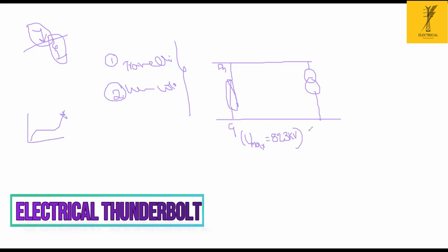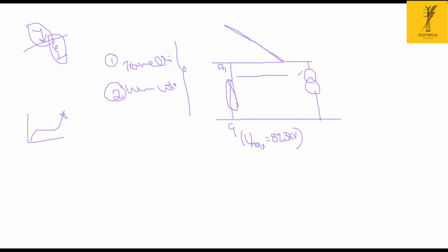So now let's assume the protection level of my lightning arrestor is 823 kV, as we discussed about these characteristics. Now a surge appeared here. Suppose the distance between these two is 30 meters. I placed it 30 meters away from the lightning arrestor. Now a lightning surge appeared here in between, and it is traveling. So the surge steepness is 1000 kilovolts per microsecond.